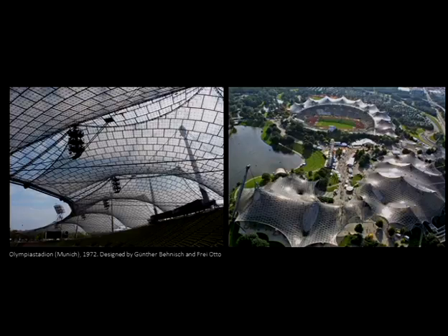So Frei Otto, with another group of engineers at the Institute for Lightweight Structures, which is actually in Stuttgart, very close to that, decided to design these roofs. They are tensile structures, but there are also cable beams and struts. All this is done out of steel, in a way that you can design through fabric models, soft bubble models, to get exactly the shape in which you get only in-plane stresses, and that is called membrane action. We speak about that again in the lecture about shells and grid shells.